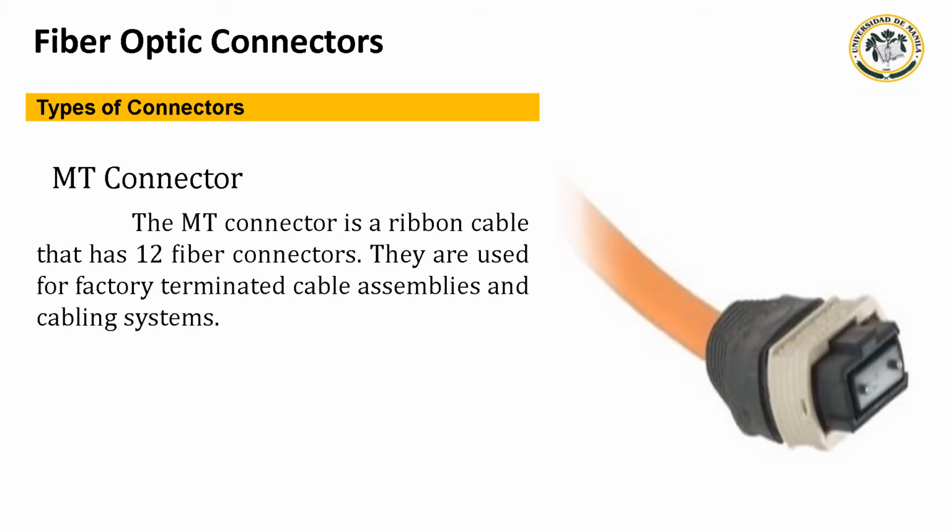Last is the MTP connector. The MTP connector is a ribbon cable that has 12 fiber connectors. They are used for factory terminated cable assemblies and cabling systems. Multi-fiber connectors are not currently designed for field fit applications, so must be lab terminated. In high-density patch environments such as data centers, they are used extensively at both single-mode and multi-mode wavelengths.